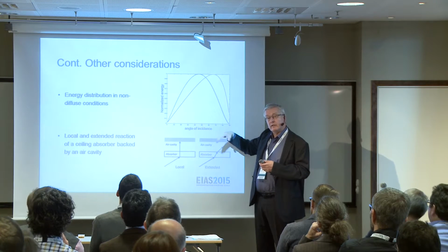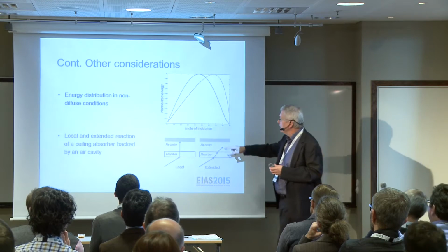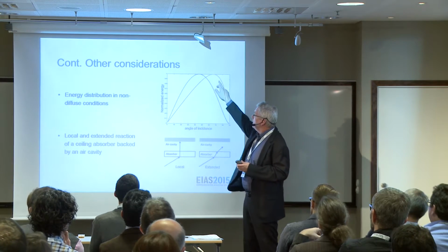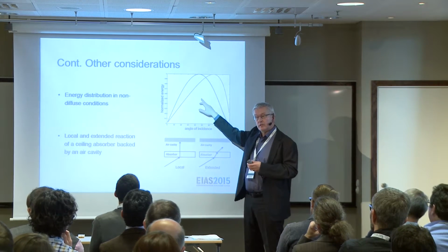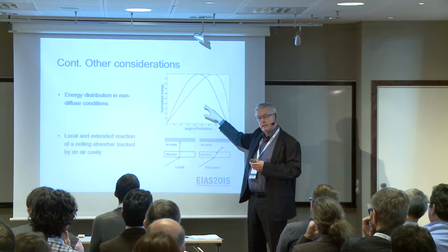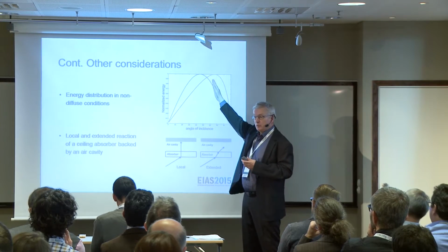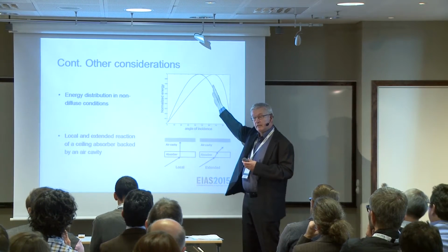But if we look at ordinary rooms and look at how the energy is distributed, it differs. So that means that even for the non-grazing group, we don't use the statistical absorption coefficient. Instead, we use an absorption coefficient corresponding to this angle.